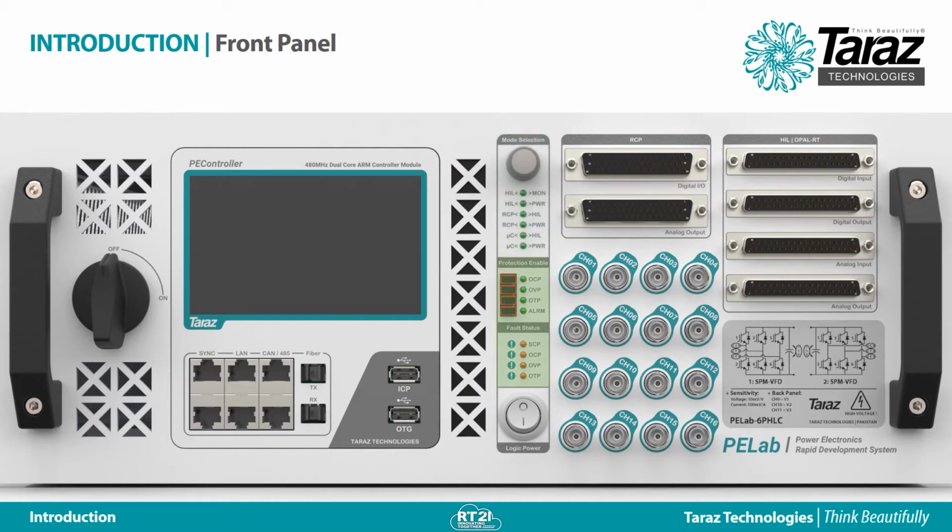We also added dedicated hardware protections in the PELab. The protections include overcurrent protections on the outputs, overvoltage protections on the DC links, overtemperature protections on the power modules, and short circuit protections on the switches.